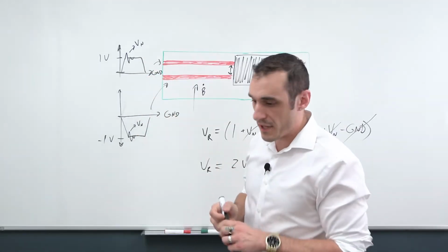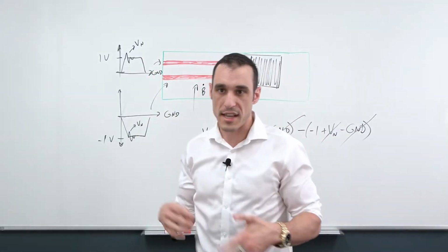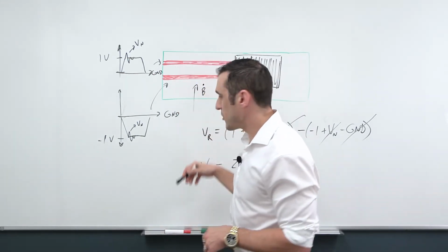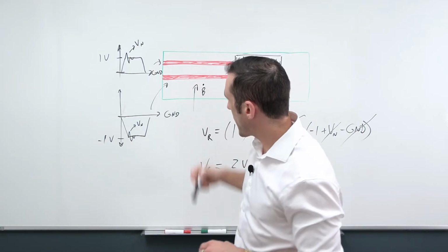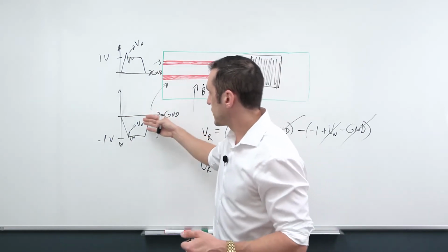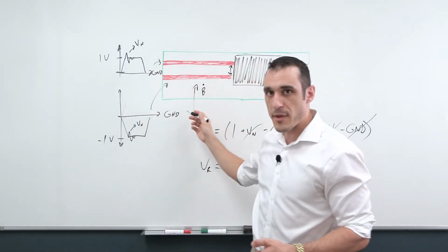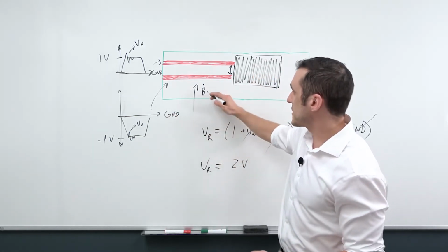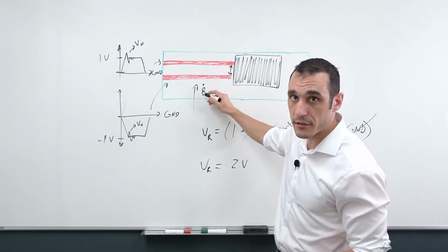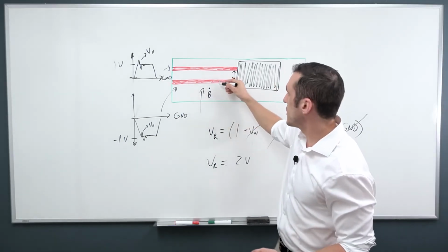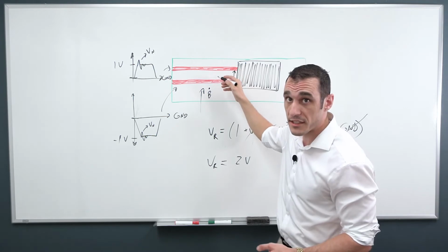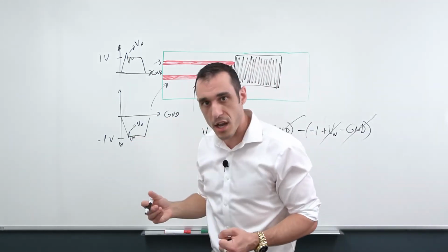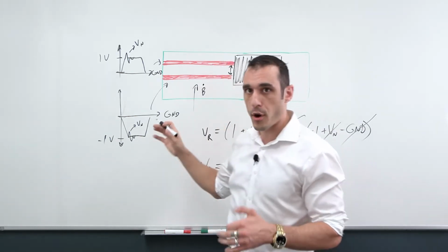So this is really important because there are actually two different types of noise that can appear in PCBs. There's common mode noise and then there's differential noise. Now, common mode noise is really important in differential pairs because, again, you can cancel it, and it's the type of noise that you would expect to see when you have some other trace elsewhere on the board that creates a very large changing magnetic field. And that would then induce some noise in both of these traces simultaneously. And that's the noise that you want to cancel out, because that's the noise that typically appears as crosstalk from some other part of the system.